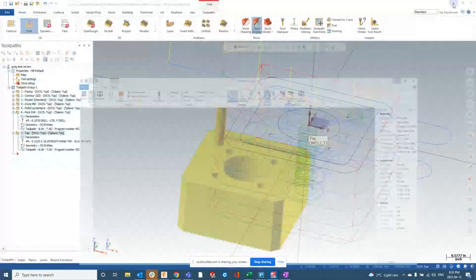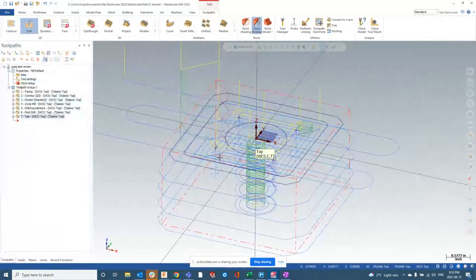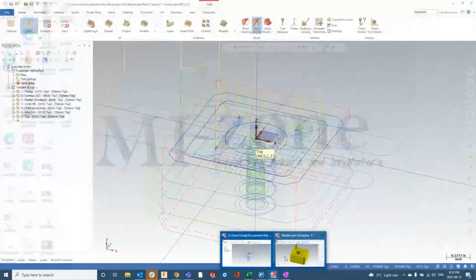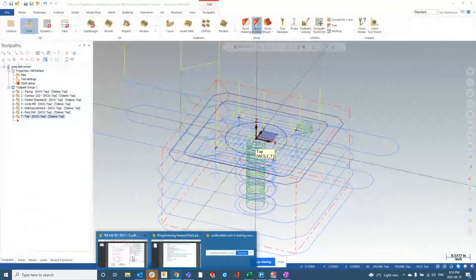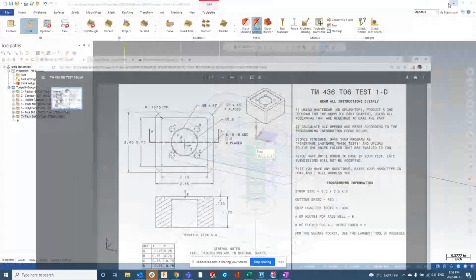The last thing that we've got to do is just do a chamfer. In this case, let's do 2 chamfers. I know on the test you guys only have to do one, and my test is on the inside, but let's do one on the outside as well. It's calling for a 40 thou chamfer. So we'll do one on the inside of the circle and one on the outside, just so you guys understand the difference.